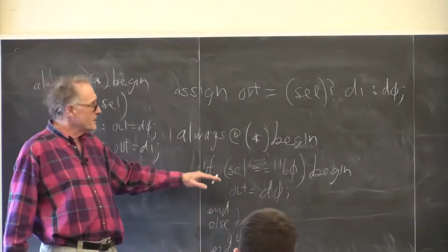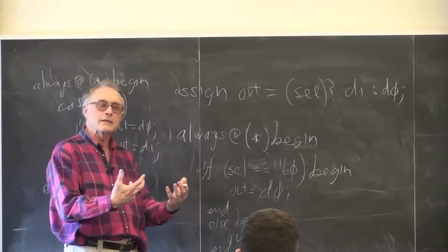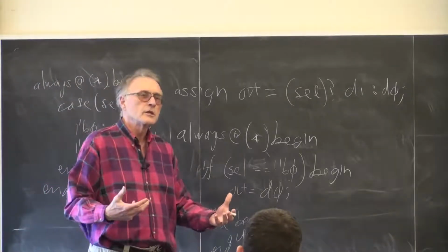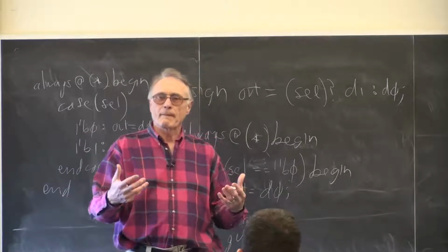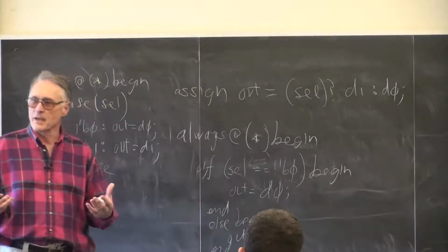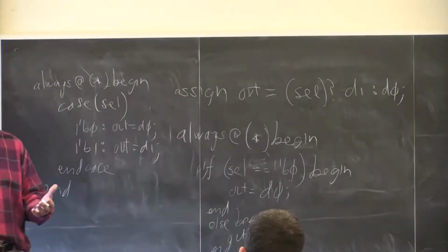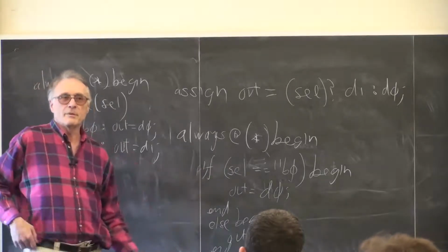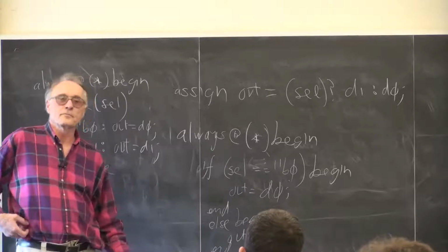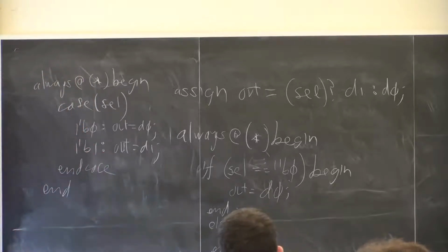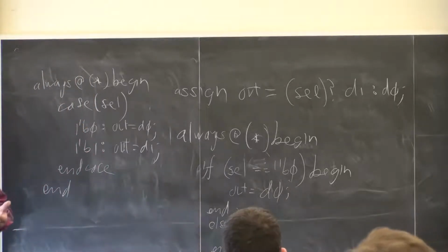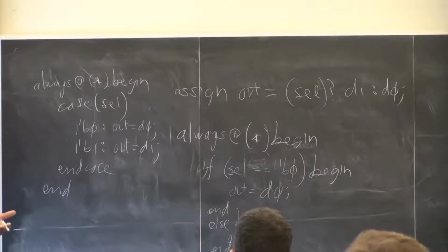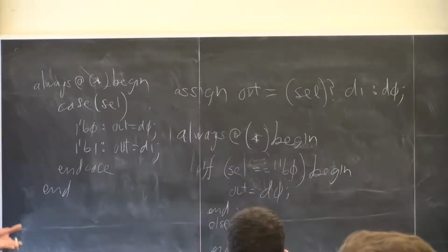If, however, the mux depends upon some complicated logical condition which is hard to express except as a logic expression, then an if statement is going to be the obvious choice. So use whichever one gives you the most expressiveness and easiness of understanding, because they all synthesize to the same thing.